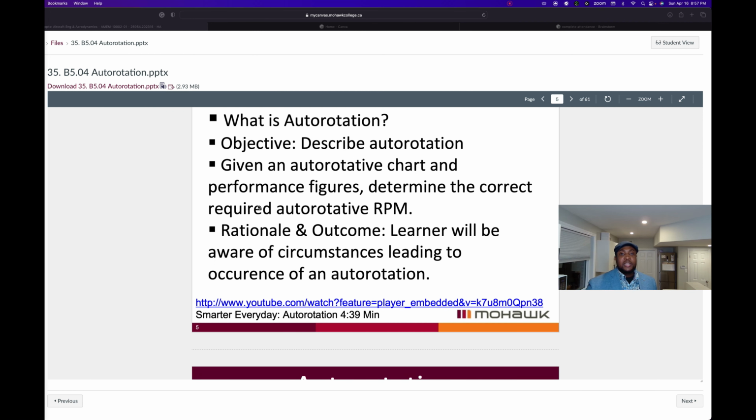This is one of the procedures that a pilot would learn, and I would expect you to recall, that when we lose engine power, the first thing that happens is the main rotor is automatically disengaged from the turbine system or the engines, the power plants, to prevent counter drive.